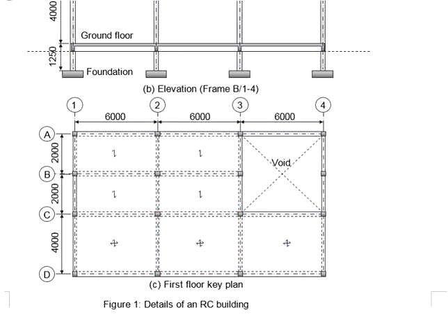Now, because of the load distributions, particularly if you are talking about this beam, you will expect some loading acting on the beam here, but no loads will be acting here, since the loads will be entirely distributed to the longer span. As for the void, there won't be any beam and slab. Thus, theoretically, you will not expect any loads acting at this region.